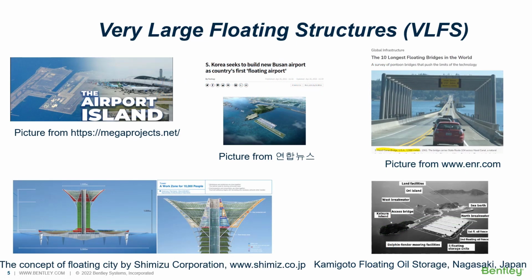This means we need to consider the elastic response when analyzing these kinds of very large floating structures. Here, floating airports, bridges, cities, and some oil and gas terminals. These are the structures where characteristic length is larger than the wavelengths. So in this regard, characteristic length could be the definition of the very large floating structures, in a mechanical sense, and could be the criteria about when we need the elasticity for hydrodynamic computation.